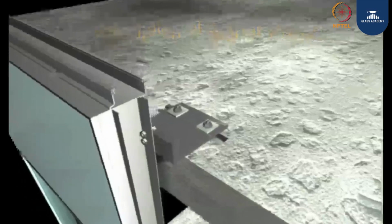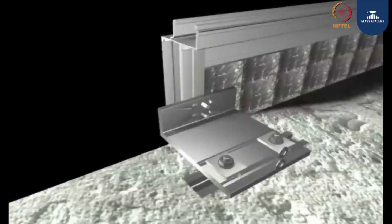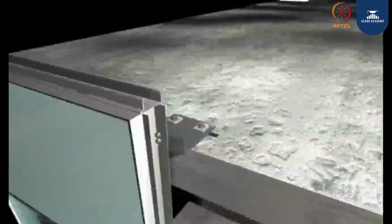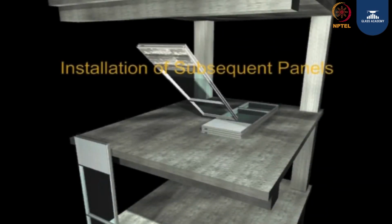Imagine this panel that you see here has 3 glasses plus spandrel plus. All the other systems, you install all these at site. What you see here is, okay, you have 1 glass, 2 glass, spandrel. Unit system you do it in factory, you bring them all together and you put it up. But the other systems that we saw before, you just do the grid, you put all the mullion, transom, then you do the glass piece by piece at site.